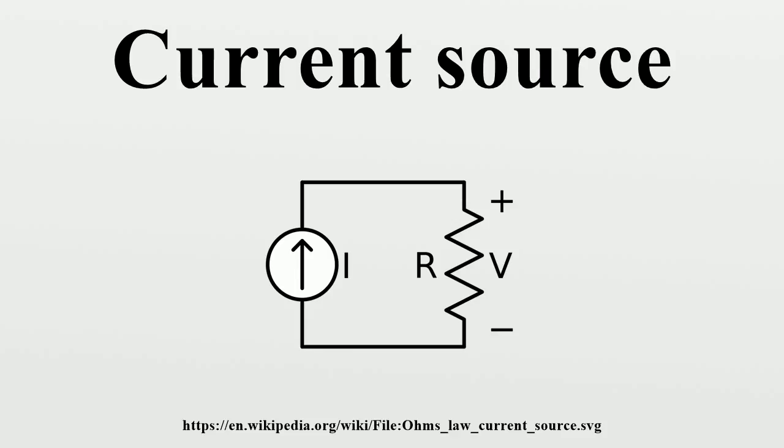The circuit to the left overcomes the thermal problem. To see how the circuit works, assume the voltage has just been applied at V+. Current runs through R1 to the base of Q1, turning it on and causing current to begin to flow through the load into the collector of Q1. This same load current then flows out of Q1's emitter and consequently through R_sense to ground.